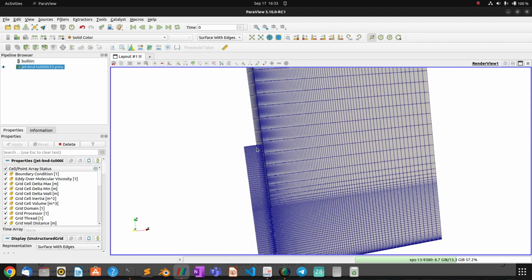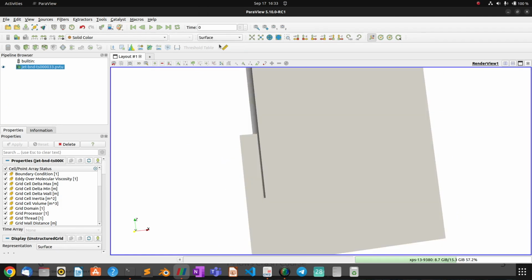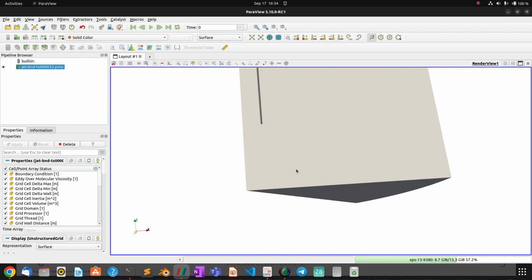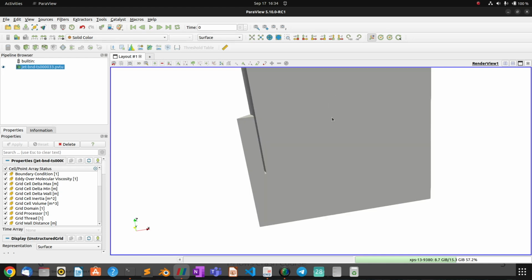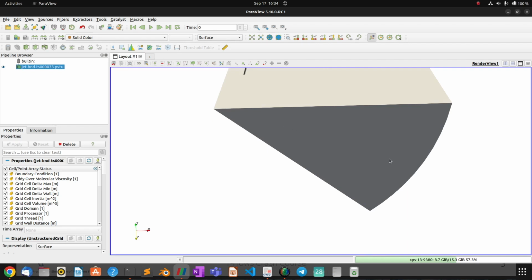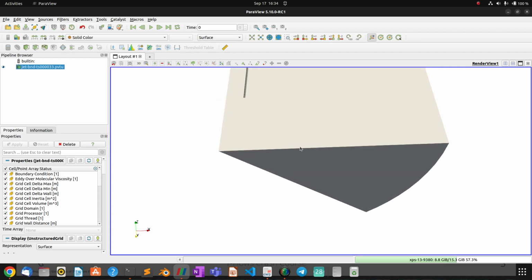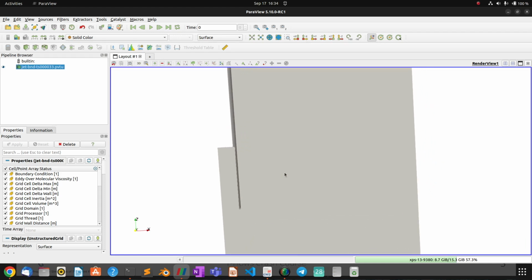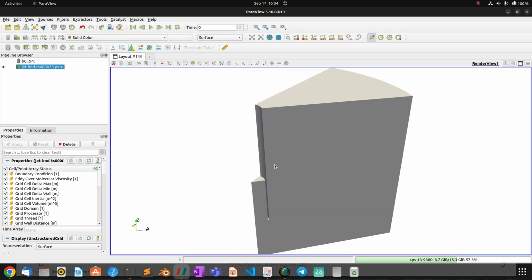So you can kind of expect what the solution would look like. We have an impinging jet here. What happens on the floor is that we have a hot plate, or a hot bottom floor, and this wall is kind of cooled down by the upstream flow, and then it goes back like this. Then what we're expecting is to see the flow circulation, but also to see the temperature changing a bit here, and it kind of sweeps, or crawls, the temperature drop in this direction. So it's an interesting problem to see, and also to analyze.